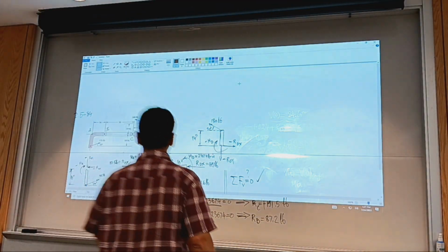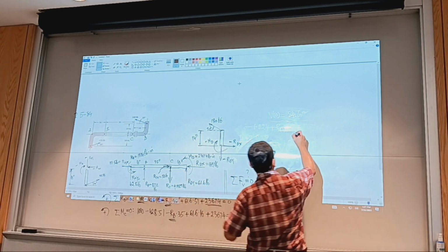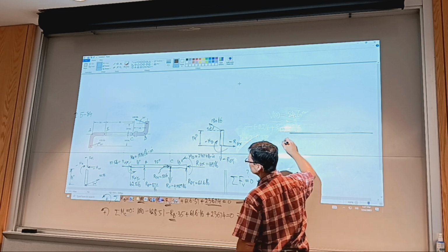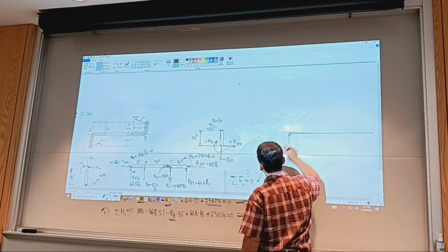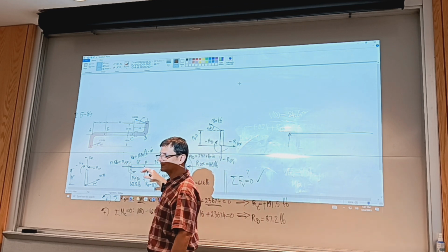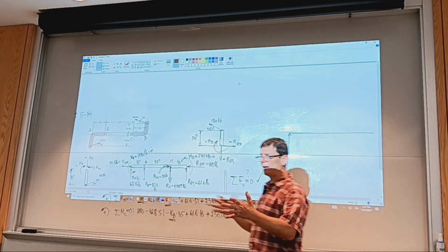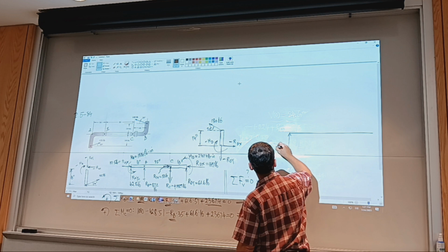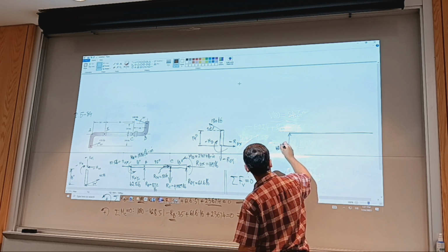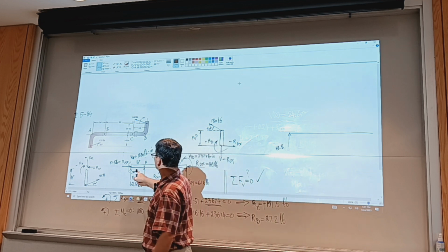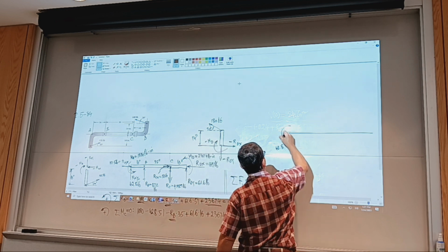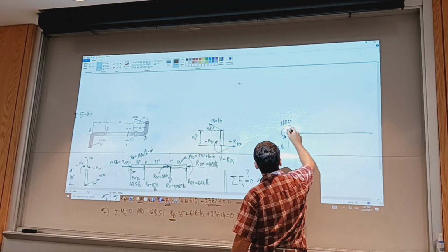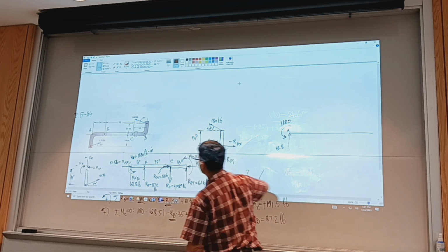Okay, so I'm going to redraw this like here. All right, and no horizontal forces. For that, we can draw an axial load diagram. We'll do it after this. So I have 42.8, and then the moment. I need to show the moment. It's 1880, and this is point A. I move to point B.